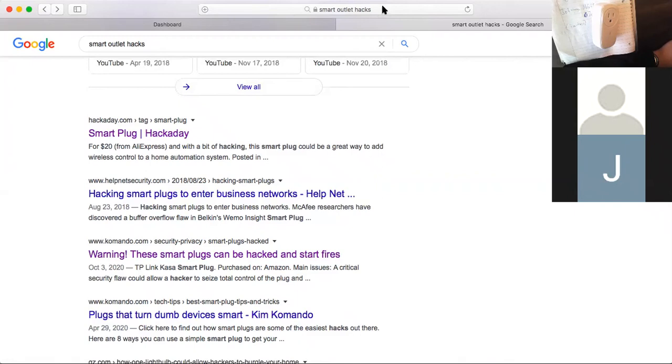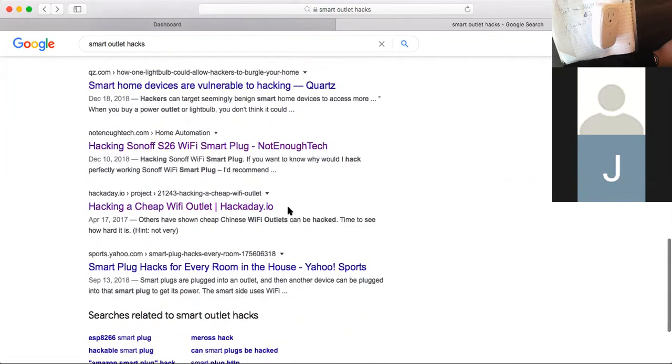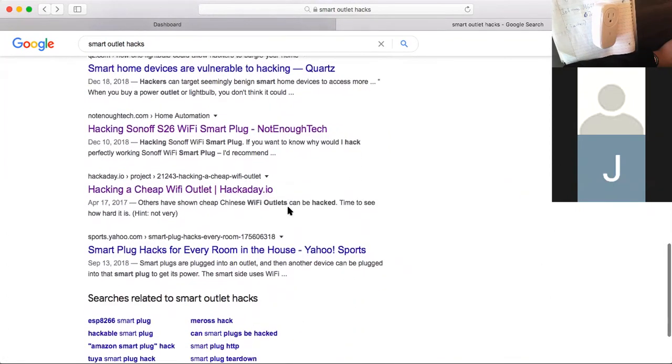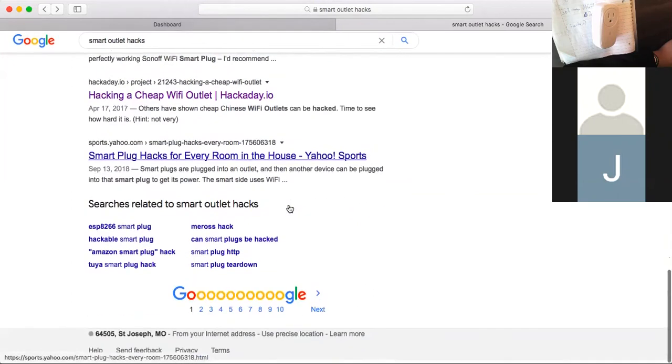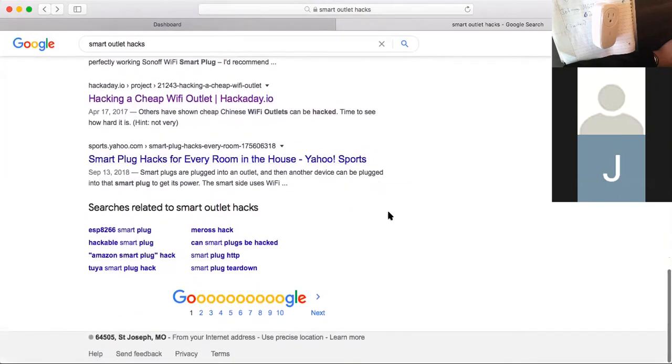Because a laptop generally needs a lot of power, so the most good idea is to use a small computer like a Raspberry Pi, which needs little power. You can just plug it in 24 hours a day. So a Raspberry Pi is a pretty good candidate for an MQTT server. They don't even call it a server, because a server generally means a very complicated program. They call it a broker, MQTT broker. The MQTT broker is the guy who handles all the messages.